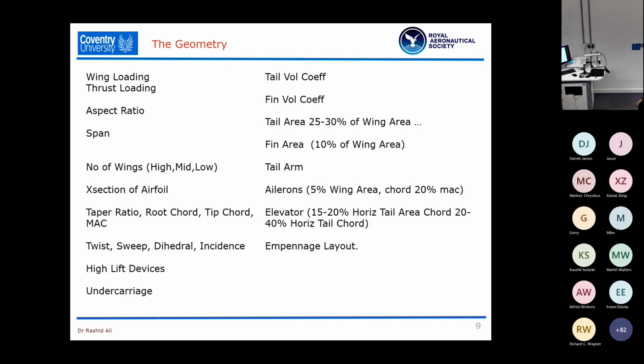The principal function of the empennage is to provide the aircraft with the ability of two rotations. One rotation is in yaw and the other rotation in pitch. Now, without those two rotations, the aircraft is unflyable. So the empennage design is rather crucial.